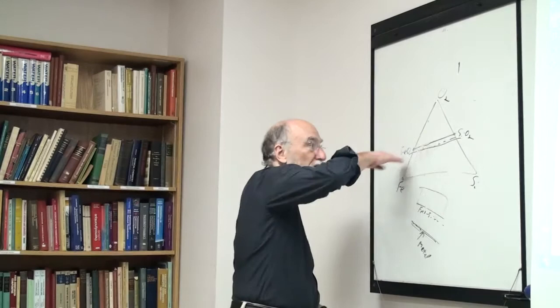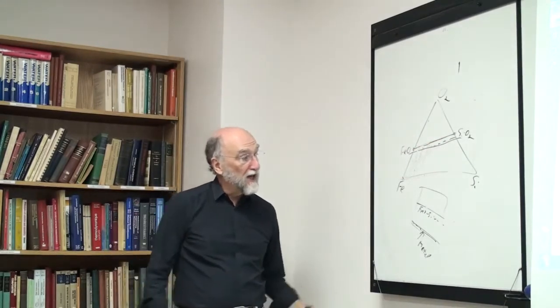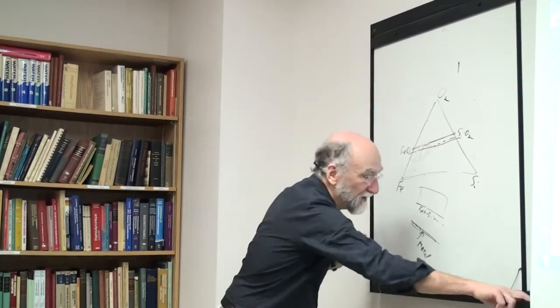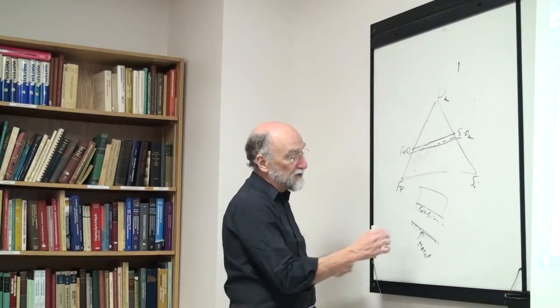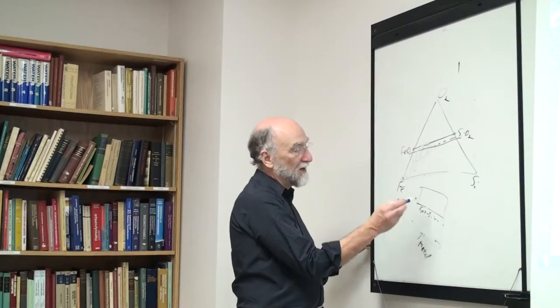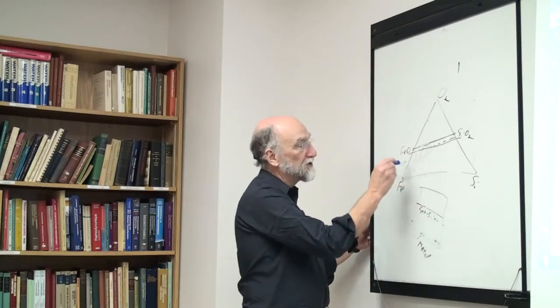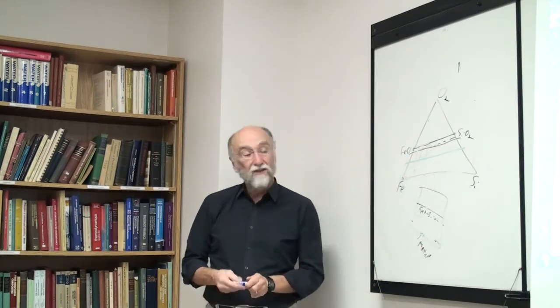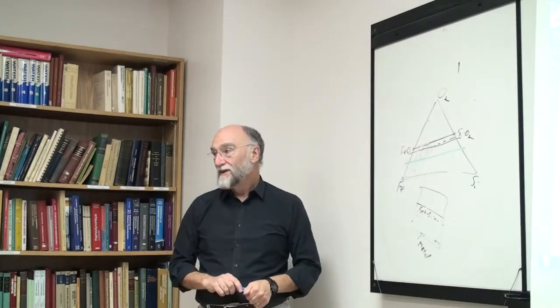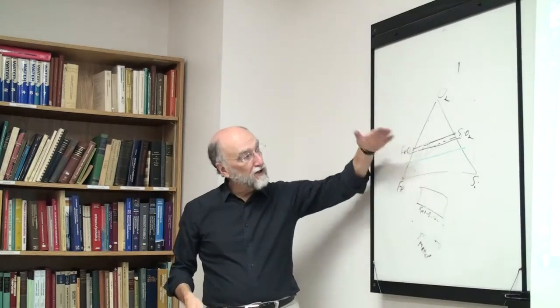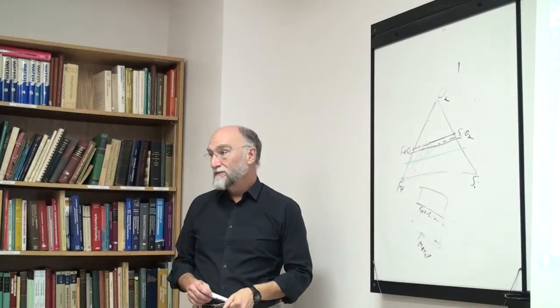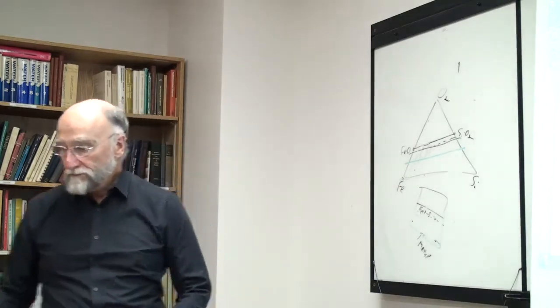The real situation is you're somewhere here. In fact, in a real slag, you might have a very large amount of metal. In a real situation, you might consider the total amount of FeO, silica, iron, and silicon in your system, and take the actual isoplethal section across the whole diagram, and then the diagram would give you the oxide phases and the metal phases in equilibrium. Okay, so you can see that with interpretation of oxide diagrams, you've got to be careful.